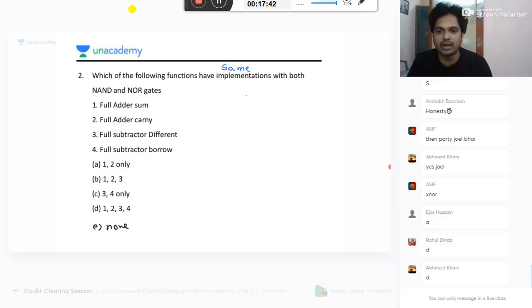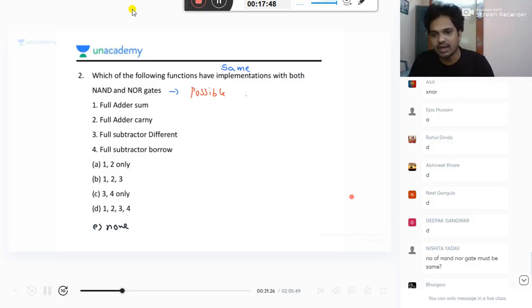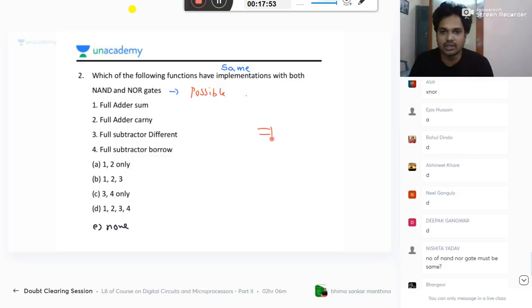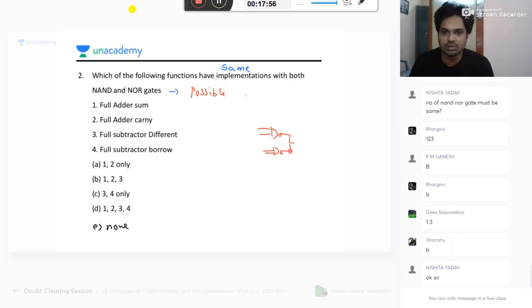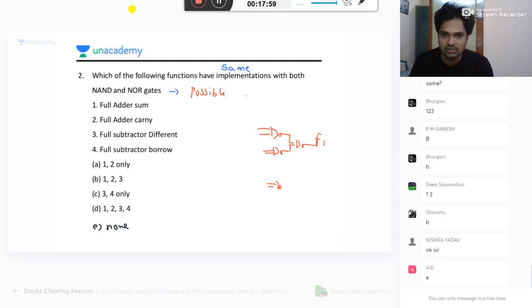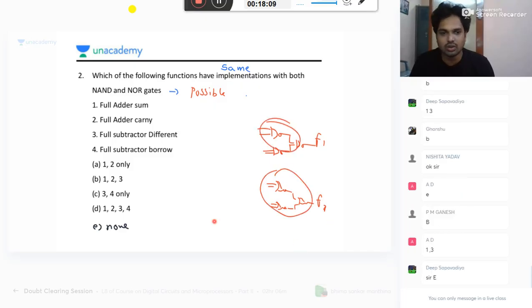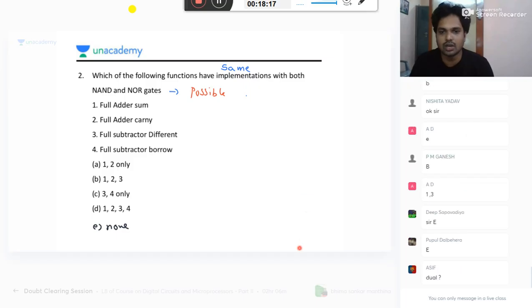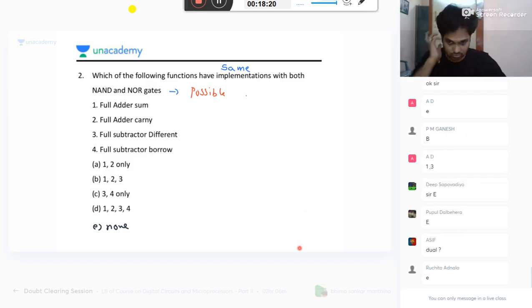Now second clock. Please understand, second clock 0 1. 0 1 means you get 0 1. This 1 will go. You should not analyze immediately 1 1 as the output. Please listen. You applied the input, you got the output. This feedback will go back but will not affect the output until you apply the next clock. Now it will read 1 1. What is the answer you get? Previous bar, that is 1 0. This 0 will go back, but it will wait for the next clock pulse, because a flip-flop will change only once in one clock pulse.